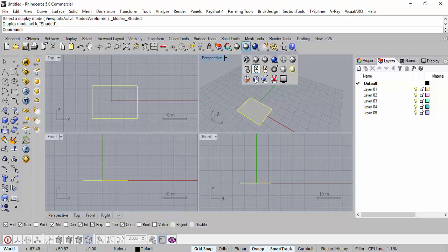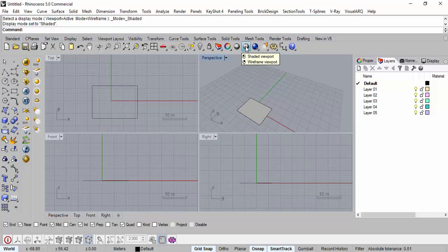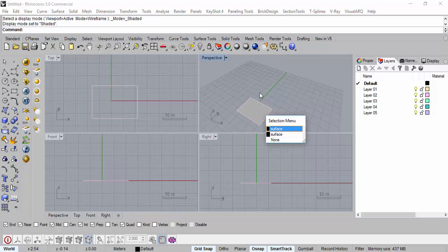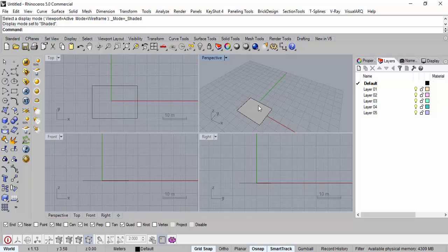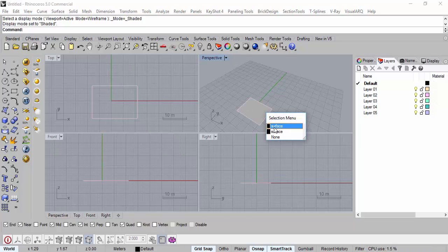Shaded mode. And just click once on it. If you right click on it, it goes off, it becomes a wireframe. If you left click, it becomes a shaded mode. So there's a surface here. And then what do you do with it? I think I've created it twice, that's why it's showing me. So I can select one and delete. We're still left with one.